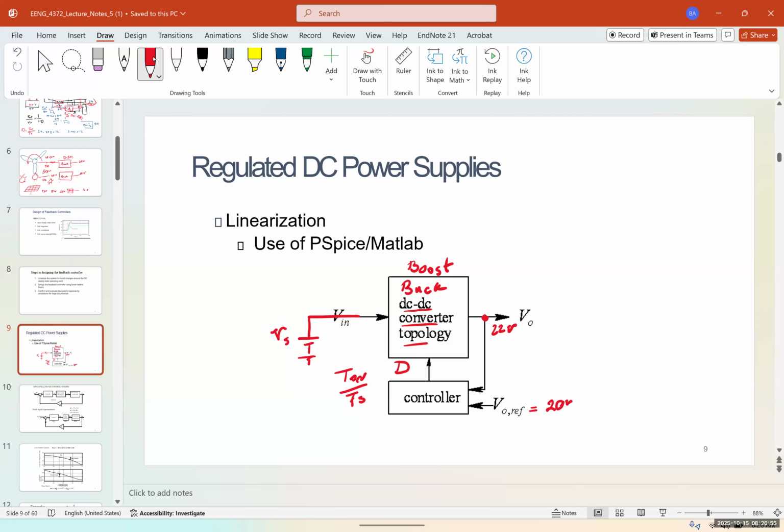So for the plots of the transfer function with poles and zeros, again, we have the same thing that we had over here. A pole in a transfer function T(s) is going to be 1 over 1 plus s over omega p.